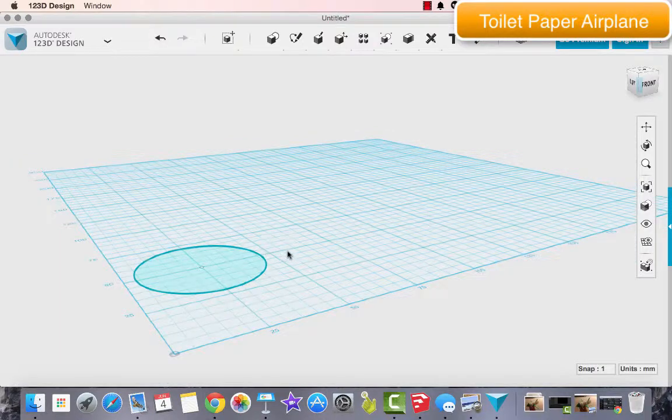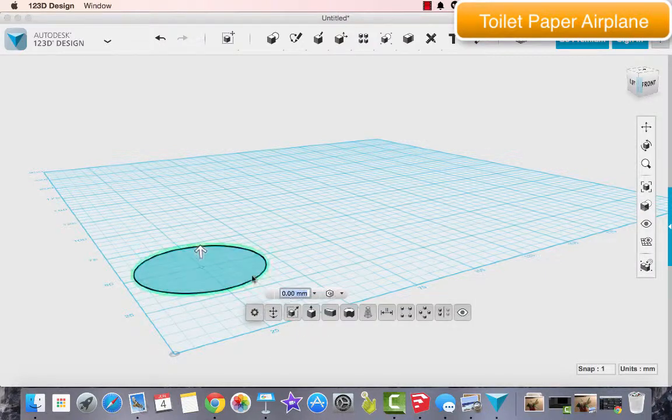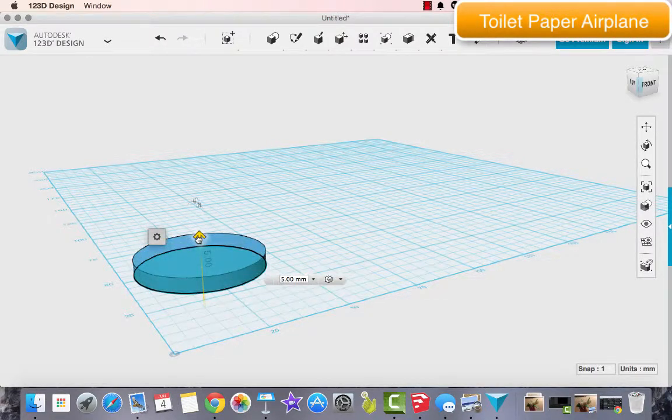And you're going to get a little bit of play, a little bit of wiggle room. You can also go much larger, so you can go 43.5 or 44 on the interior diameter, inside diameter, and go with it that way. Your choice there. Now, I don't want just a cone. I need something to be able to adhere to the inside, in my case, the inside of the toilet paper roll. So what I did was I went and extruded it 5 millimeters. Not much, just enough.